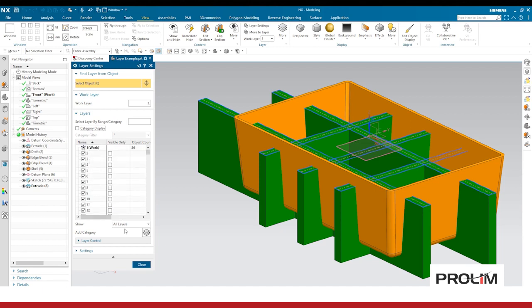Now, for all selectable layers and all visible layers, these allow me to filter out layers in my model. Say for instance I have layers specifically defined that I don't want shown, maybe some sketches or some datum points that I have placed out in space for a spline curve that I don't care to see because it just makes the screen all busy.